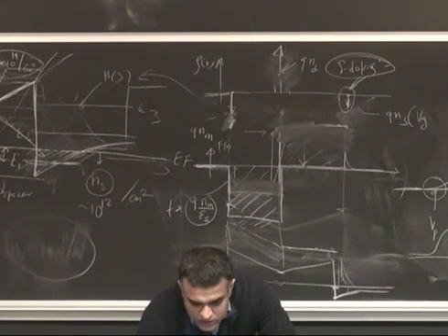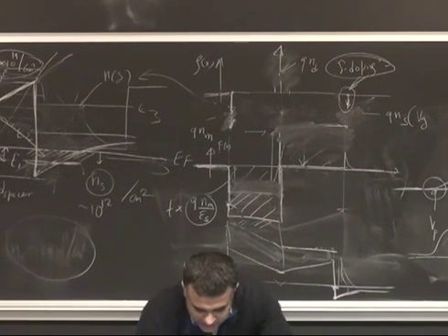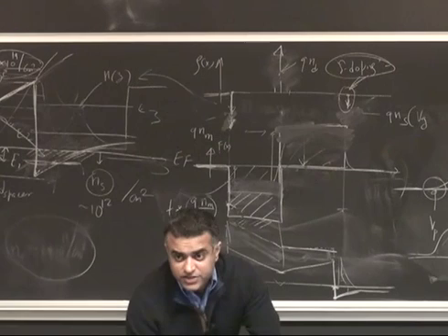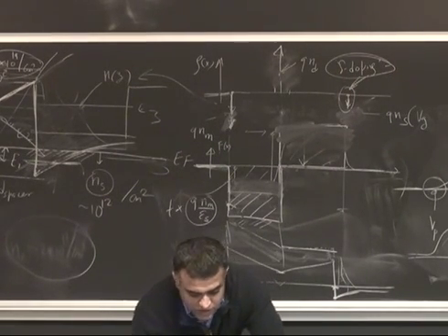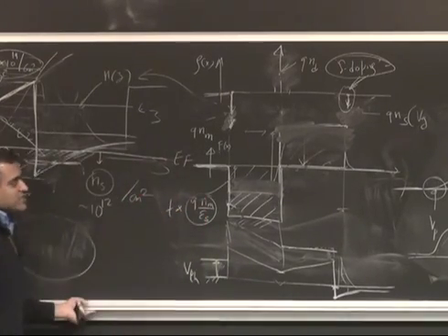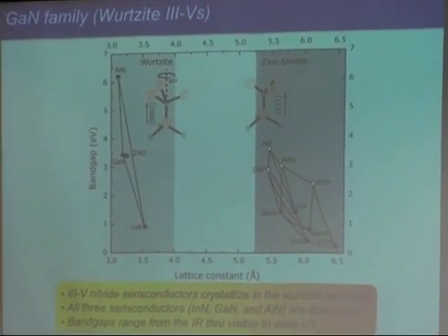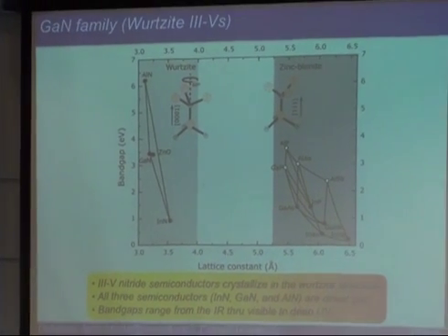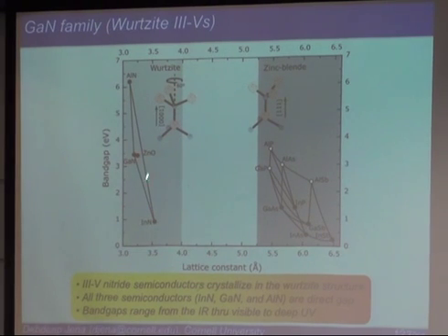Okay, so now what we are going to do is spend the last 10-15 minutes today talking about the same thing, but in the gallium nitride material system instead of gallium arsenide. This will help us look at a few specifics of this not new but relatively new material system and see how what we talked about changes. How do the things that we just discussed today, HEMT, threshold voltages, charges, change in a nitride system? So gallium nitride and aluminum nitride and indium nitride, that's the 3-5 compound semiconductor nitride family.